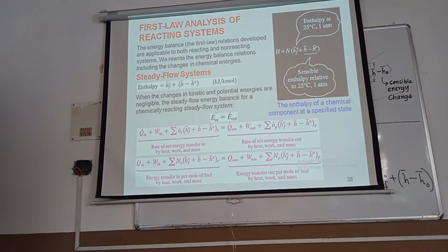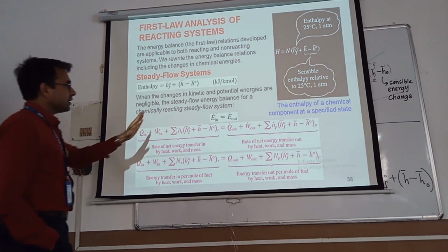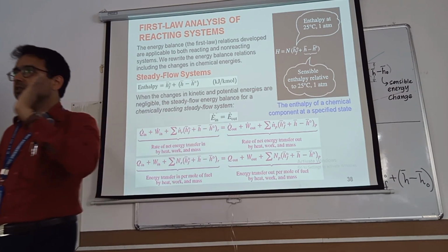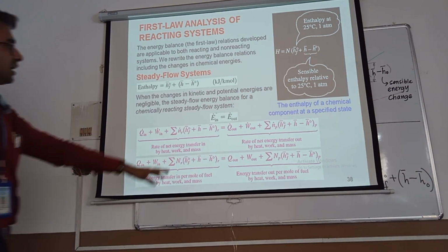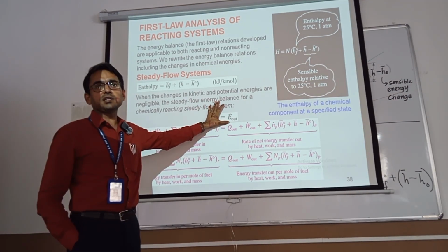Right? But for your determination of enthalpy of reaction or enthalpy of combustion or enthalpy of formation, you have to ensure that at the inlet and exit the conditions are the same. Because you have to understand the change in chemical energy only, you have to nullify the condition of state. That is why we are ensuring the conditions are the same at the inlet and exit, or the reactants and the products. Is it clear?